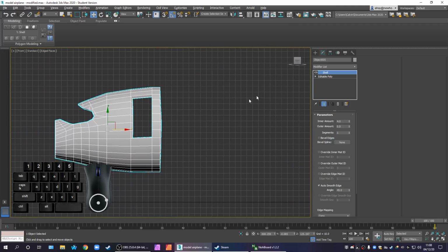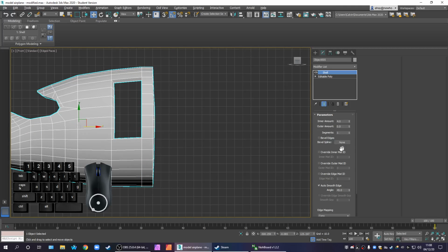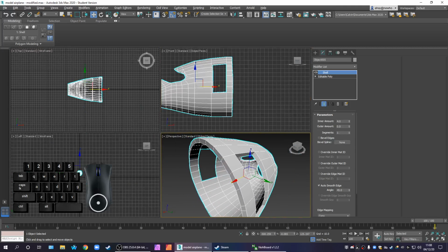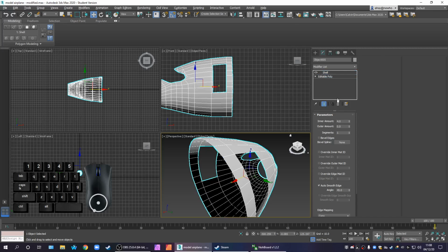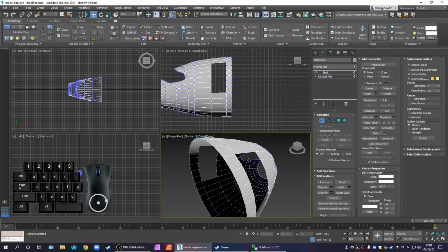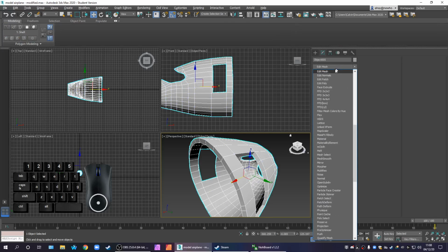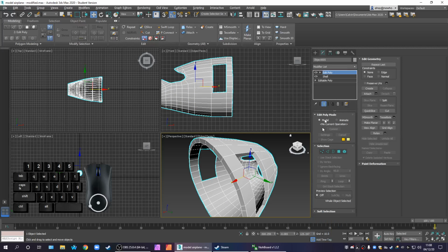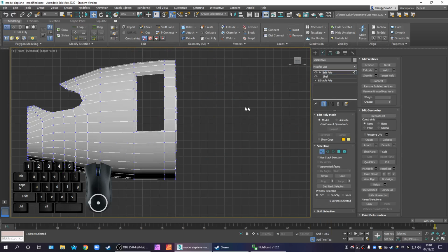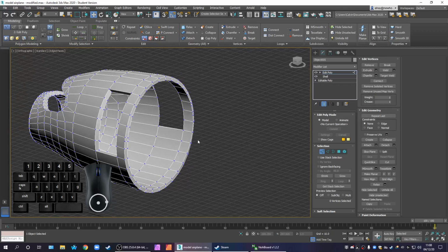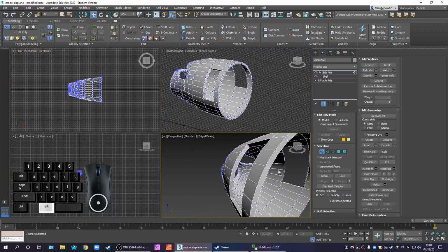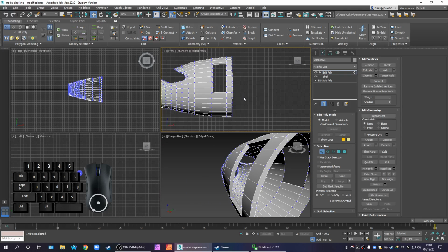And we're just going to have to correct it. Now I don't want to change any of my outer geometry, so I'm going to focus almost exclusively on the inner geometry, because I need the airplane to line up. So I'm going to put an edit poly afterwards. I need this to line up with other parts of the fuselage, so I really can't play fast and loose with the edges.